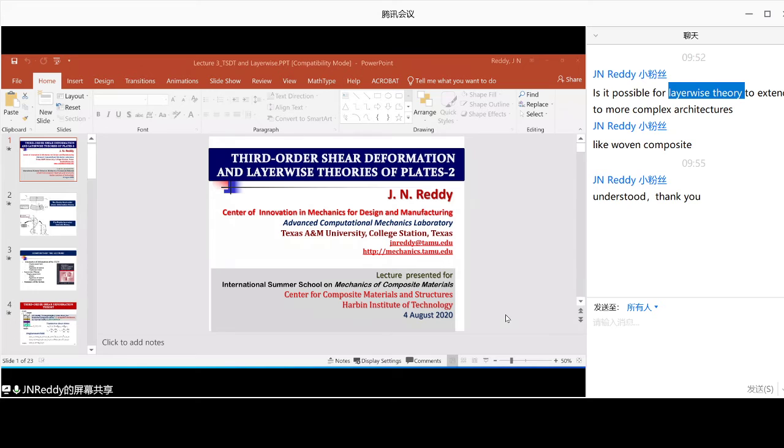It depends on the criterion you use. This is a good question, but remember, you always need a criterion. It doesn't automatically say there is a delamination. What we need is either a stress criterion or a strain criterion, which will tell you if the material has failed and is no longer taking the stress. If it is exceeded, then we allow the node to separate into two nodes.